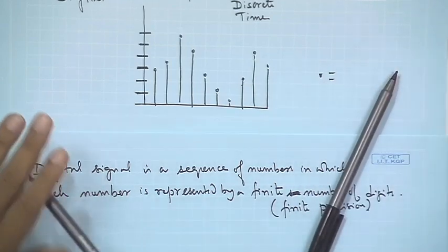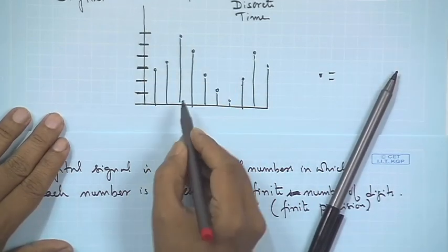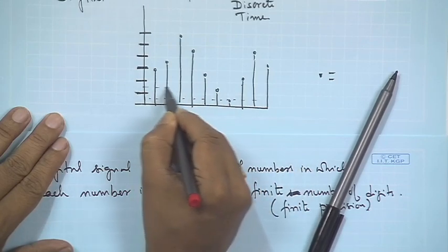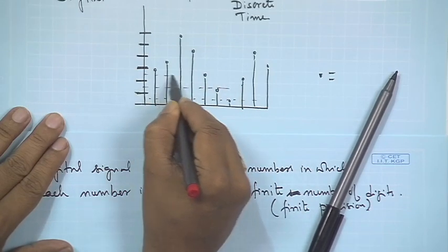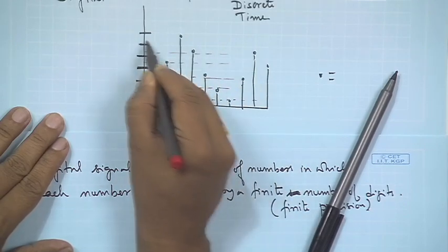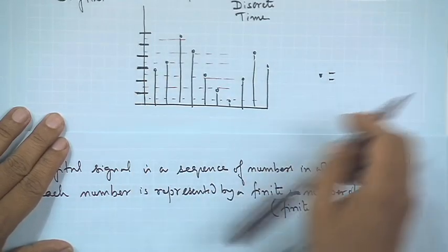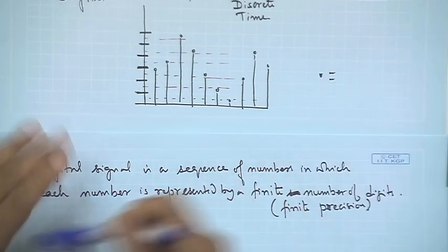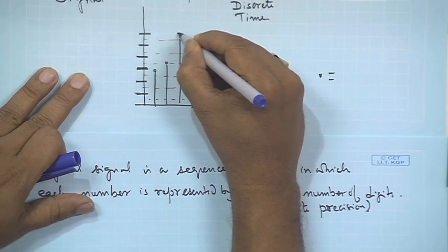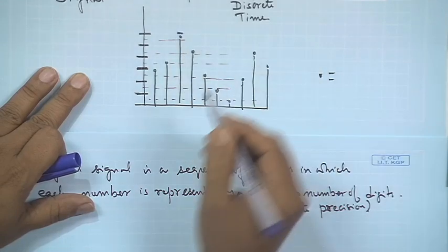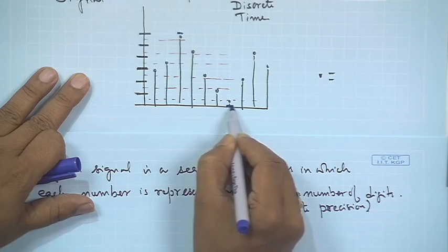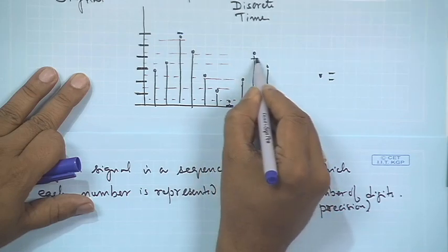Now, suppose one has decided these intervals, one can find the middle point of each of these intervals, and if the signal has gone above the midpoint, then it would refer to the higher end of that interval, and if the signal has remained below the threshold, it would refer it to that lower point.